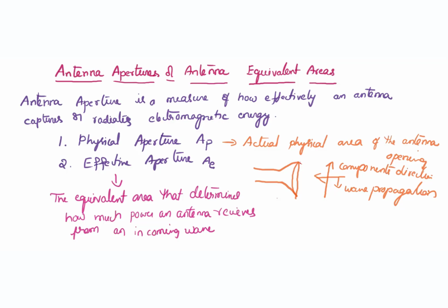But when the wave enters this opening of the antenna, when it travels on the side walls or touches the surface of the antenna, the electric field becomes zero for that case. So the incident wave is not all going to the load. Assume that there is a load Z. This is the incident wave, but when it touches the side walls, or the top or bottom walls of the antenna, the electric field becomes zero, which means there exists a non-uniform distribution throughout the antenna.